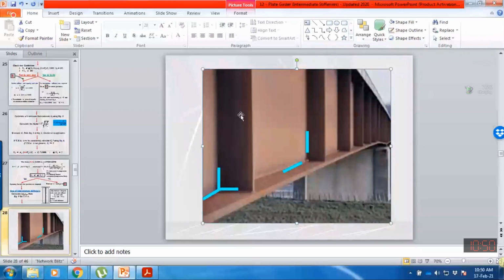So when all these three welds meet at one point, or they are merged, the shear forces which are resisted by this weld will also transfer to this weld. But this weld is not designed for this shear force. So the shear force which this weld is resisting, when it transfers to this weld, will break this weld. So it will cause cracks at the junction.